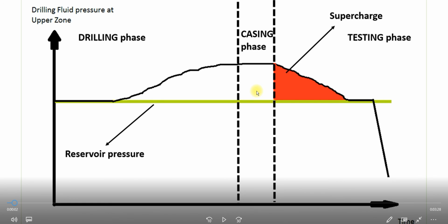And the last question is about conventional wells and supercharge. There is nothing to do with completion. The casing, whether you put a casing or not, whether you have a perforated casing or open hole condition, and that you lock the production at a higher level, that's up to you. There is nothing about mitigating the supercharge problem using different casings.